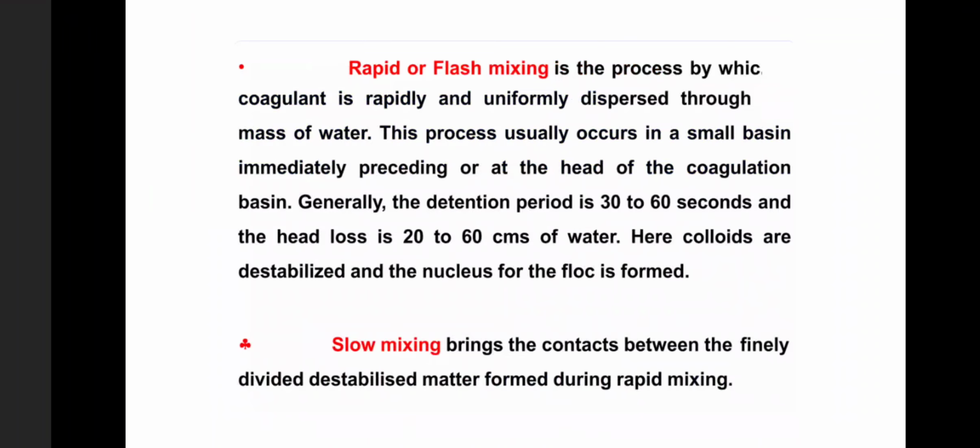So it means we are allowing the water a thorough mixing with the help of a mechanical stirrer, and then later we are collecting the coagulant on the top. For example, if you have water of 40 to 45 centimeter depth, and you add a coagulant, we allow the flash mixing in a fast manner.